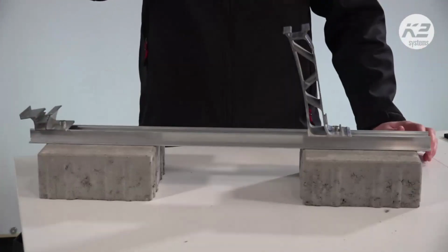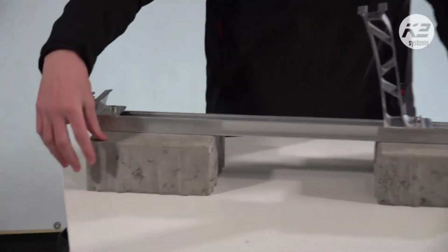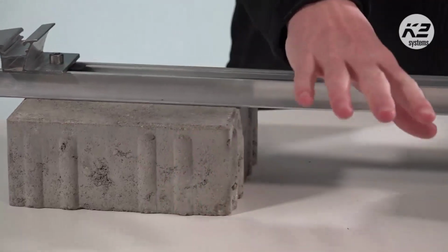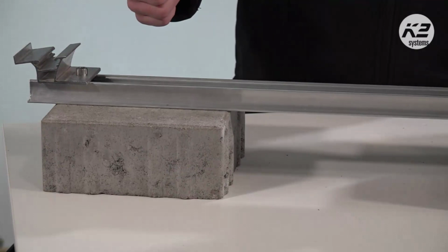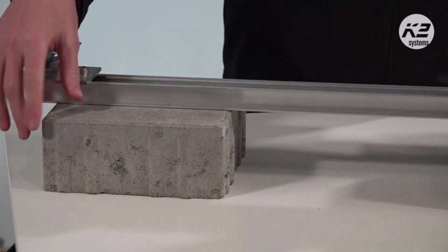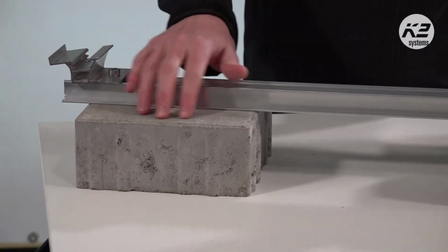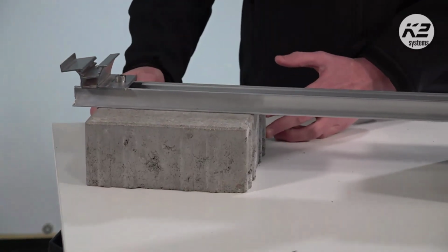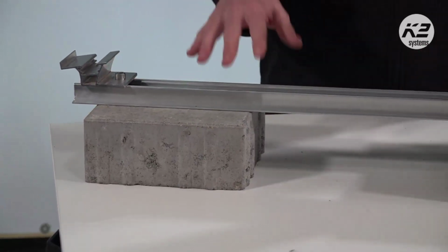All right. So there's a few things that you want to consider on here. The concrete's a little bit rough. Usually the case, you'll have a membrane and then some green roof material or some ballast on top. The membrane can be susceptible to damage. So if you are using this, you've got to be quite careful about not scratching or damaging the membrane by putting these concrete blocks on top, because they are quite coarse, and concrete is quite easy to move around. You can hear this though, it's pretty rough. And you don't want to damage that membrane.